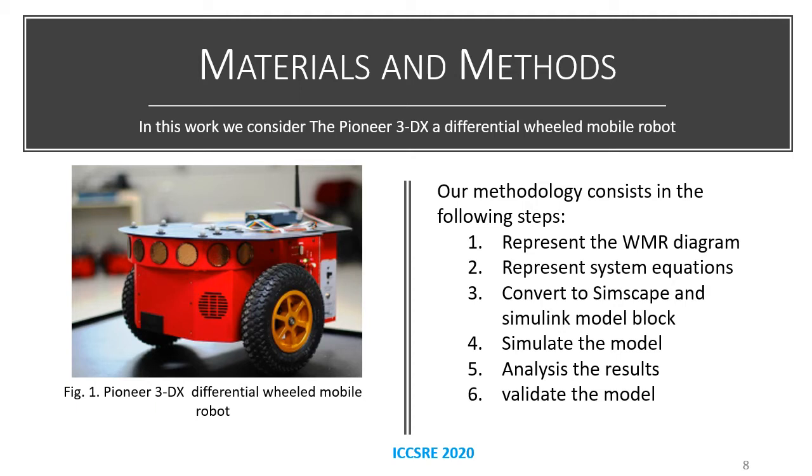First, represent the mobile robot diagram. Second, represent the system equations. Third, convert to the Simscape and Simulink model blocks. After that, simulate the model, then analyze the results, and finally validate the model.